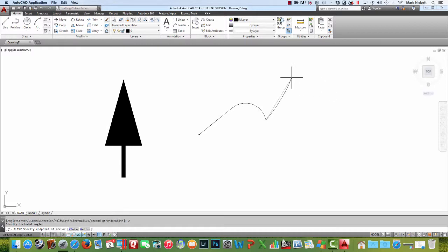So when I do that, you can see that it creates that angle from there. So I can kind of put that up there like that. And then the arcs will continue tangent to the other arcs. Quite honestly, these sub commands in the arcs are relatively hard to use. But it's kind of fun to experiment with them to see what they actually do.